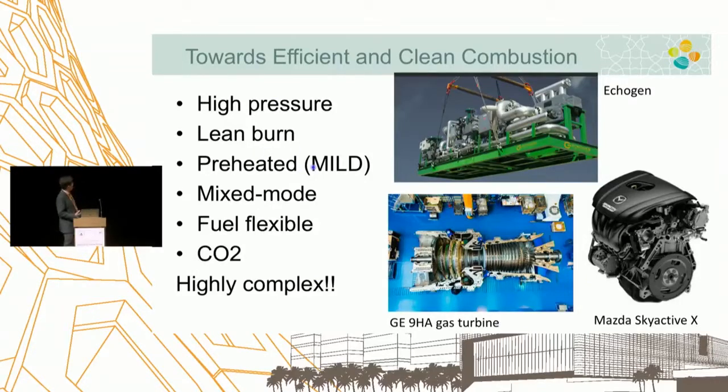You want a preheated, extremely lean condition to reduce pollutants. As you push the combustion condition to this extreme, combustion often happens in neither non-premixed nor premixed mode. Sometimes it's dominated by the ignition mode. So all sorts of complex mixed-mode combustion is happening, and I'll give you some background about the modeling challenge in dealing with those kinds of systems.